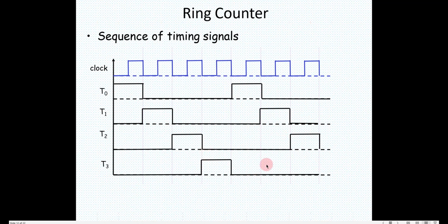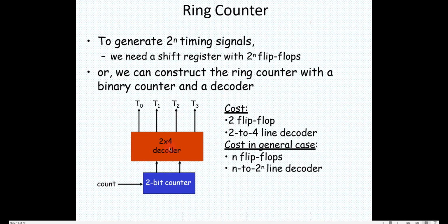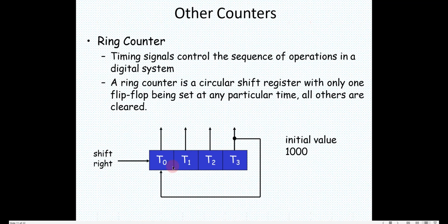Okay, this is 1, 2, 3, 4. In some circuits I require 2-phase clocks, then it will be 1 0 1 0 like that. This is a 4-phase clock, and sometimes I require n-phase clocks also. That means more than 4 also. Those types of phase clocks can be generated by using a ring counter.